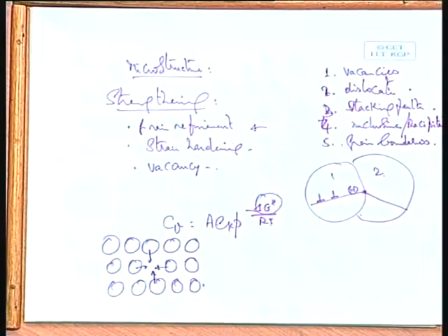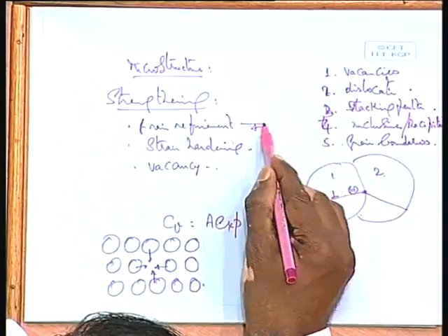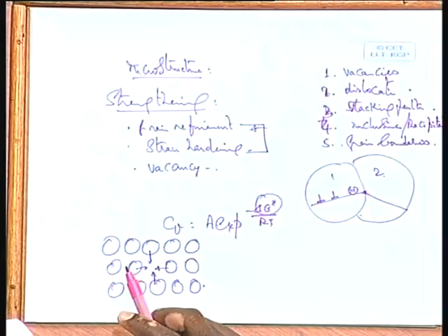Okay. So, once they are pulled, there is a compressive stress there, and that stress acts as an obstacle for a dislocation which is moving in that direction. Any vacancy can also act as an obstacle. So, this is one way, but nobody thinks of that, because the extent of strengthening that you can achieve by that is too small, and as a result people do not take it as a design criterion to improve the strength of a material. But the most crucial are these two as far as pure metals are concerned.